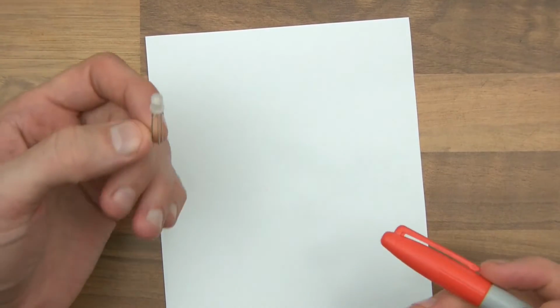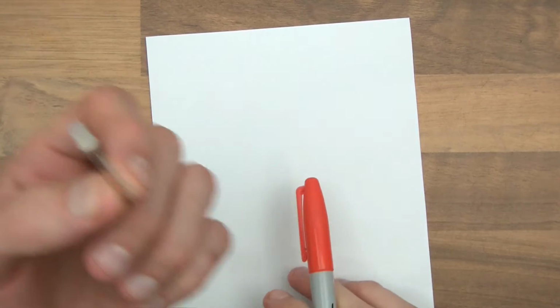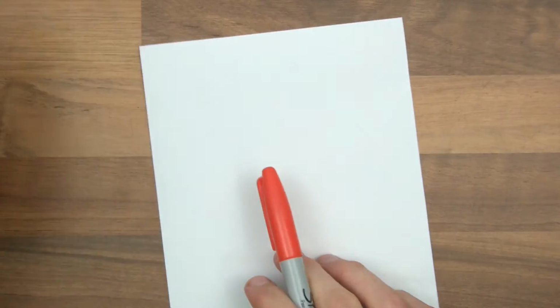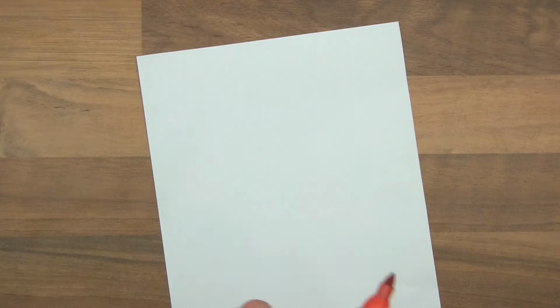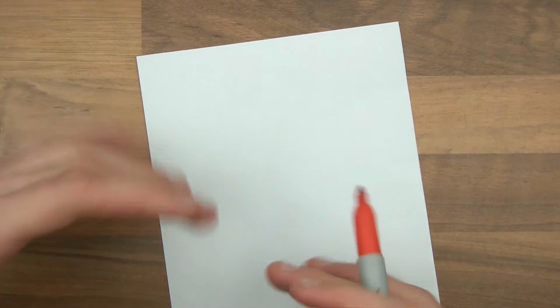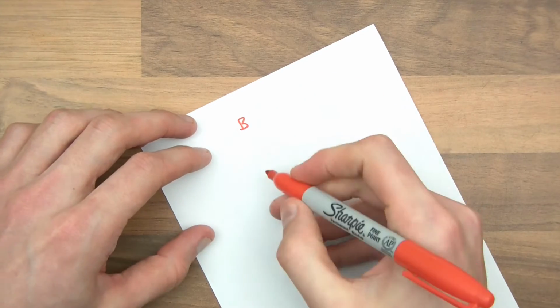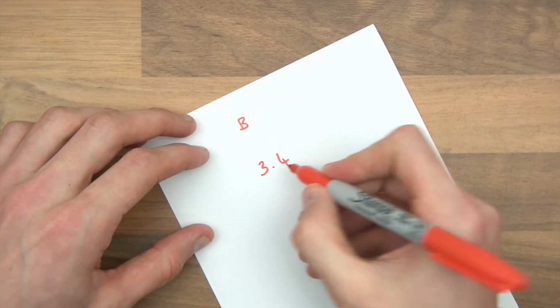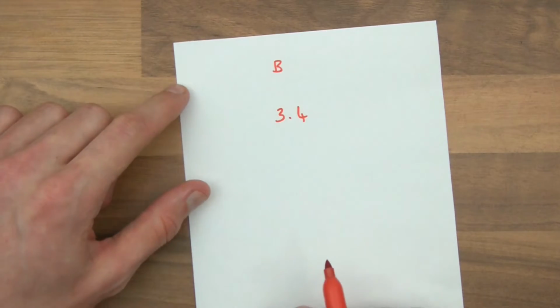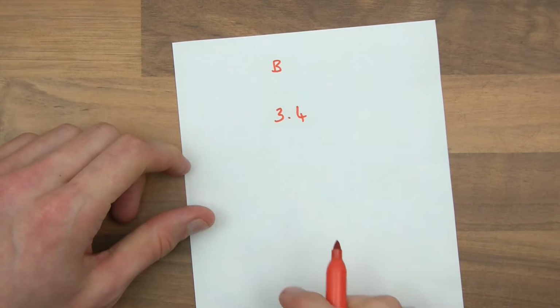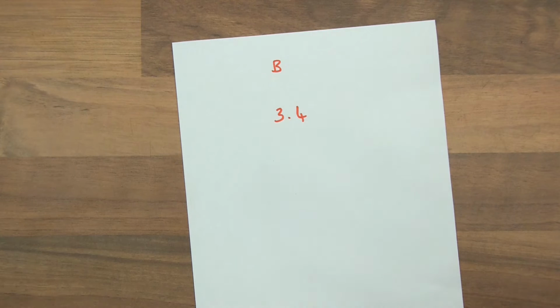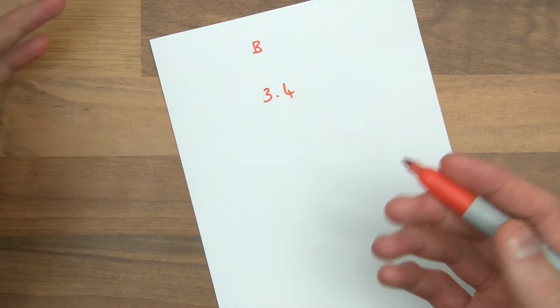Now let's say I want to power the blue LED, or the blue component of this LED. So the forward voltage of the blue LED, usually you'd use the spec sheet to work this out, but I know for me the blue one is 3.4 volts forward voltage. And I also know that I want to draw about 20 to 30 milliamps. I want to draw 30 because I think it can handle it.